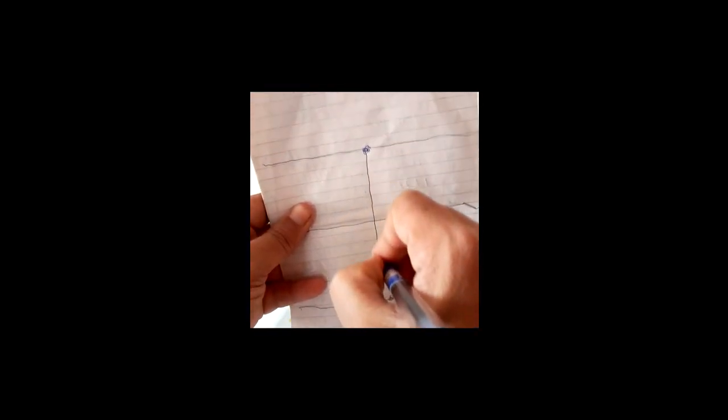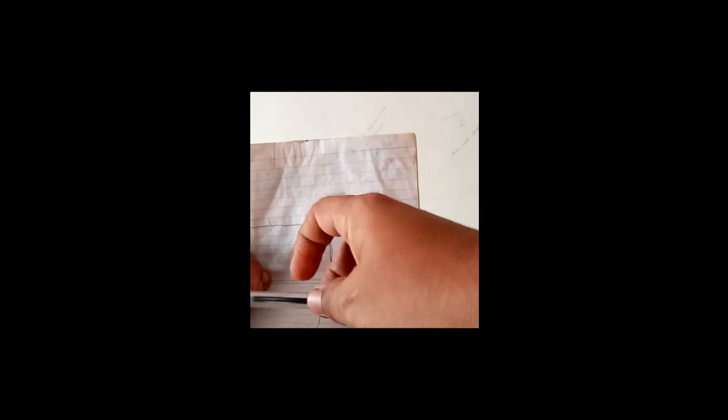And after rotating it, you can say that these two points will be on a straight line, a straight line which is perpendicular to the XY line. We need to understand this in a better way. If we project it to here, and project it to here, it will form a rectangle. So it will form a rectangle like this. And if you fold it like this, then this will form a straight line. That rectangle will be folded into a straight line.